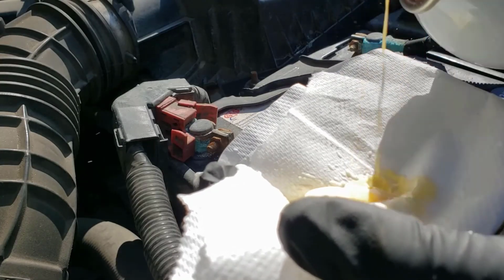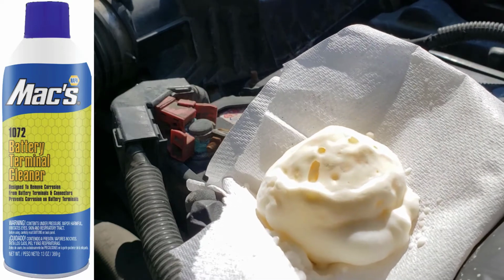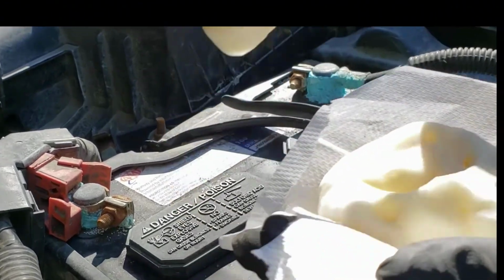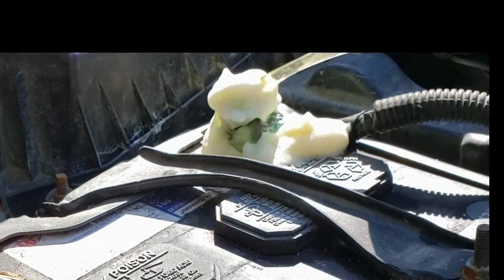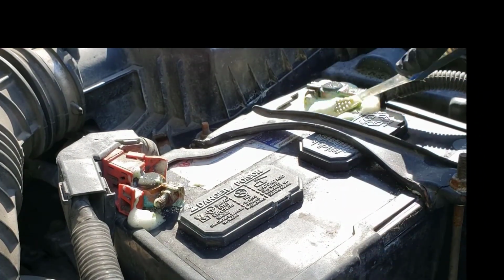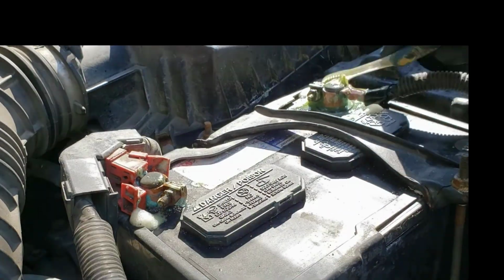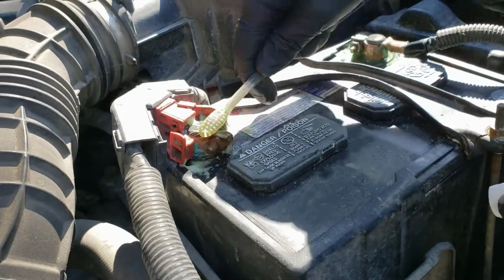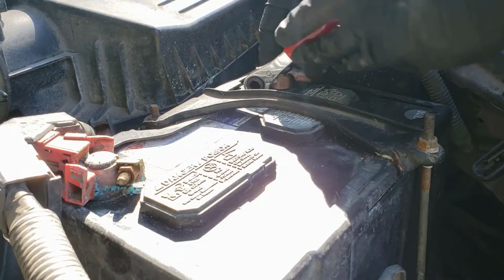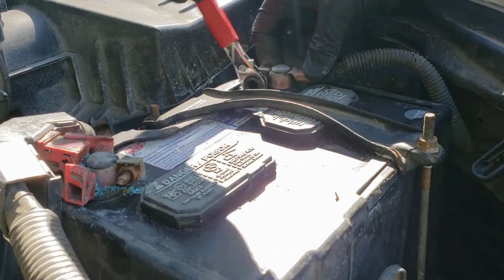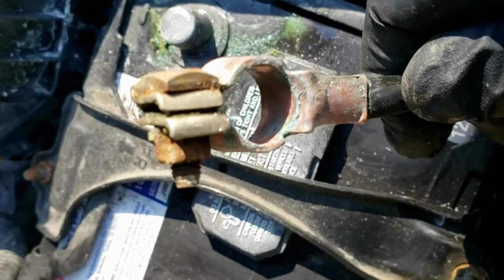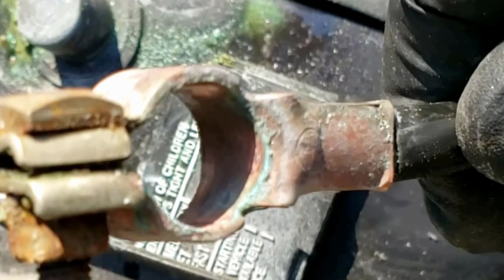And then I'm going to spray some commercial cleaner into a rag. And I'm going to work a toothbrush in. And I'm going to cover it onto the actual terminal. And work it in. And you can see it working right away. It's neutralizing and cleaning the acid off of the terminal. Once that's clean, I'll bring in a ratchet, loosen the terminal, remove it, and you can actually see how the corrosion has built up inside the terminal itself.